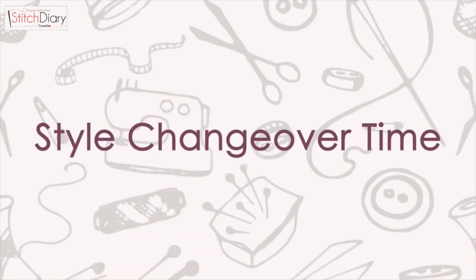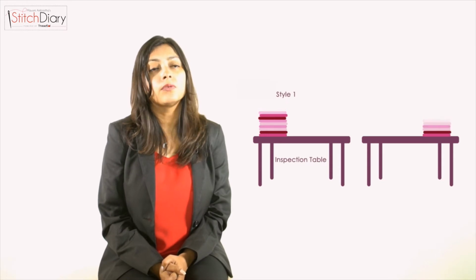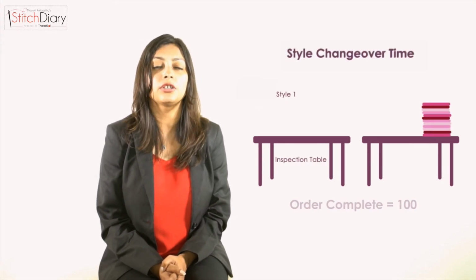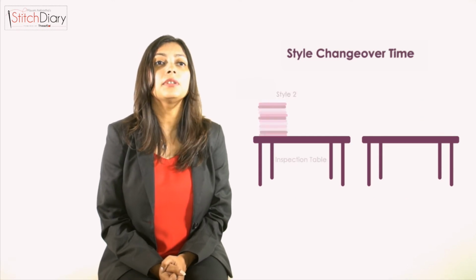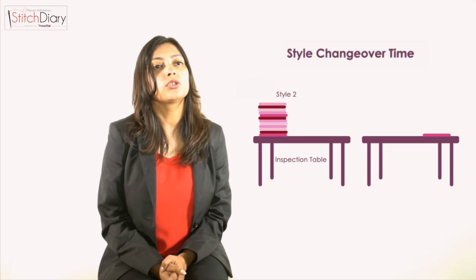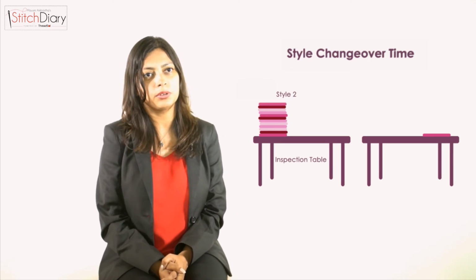Style changeover time is the time it takes to complete the entire manufacturing setup from style 1 to style 2 as per the accepted performance and quality standards. It can be measured at the end line inspection from the time it took for the last good piece for the first style to come out and the time it takes for the next or first good piece for style 2 to reach the end line inspection table.